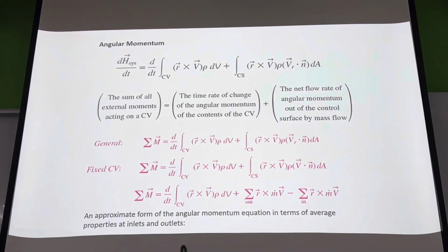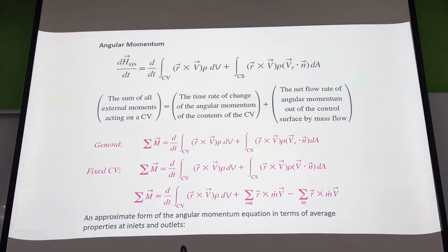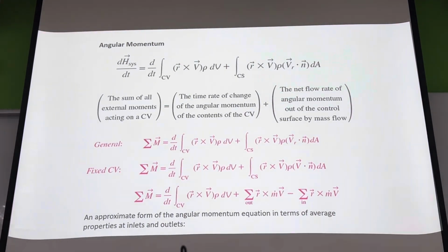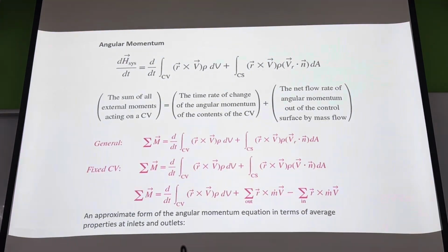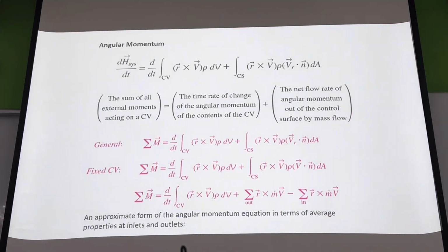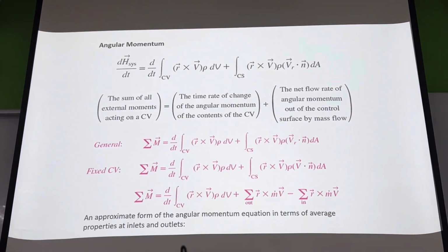Imagine if you had a straight pipe, and you had fluid all flowing at the same velocity. You have to assume that all that fluid is at the same radius, because if I'm taking the momentum at this point up here, they all have different radiuses, and so you'd end up with different rotational momentums. So you have to assume that the pipe is relatively narrow. You can do it with an integral form, but it gets complicated.